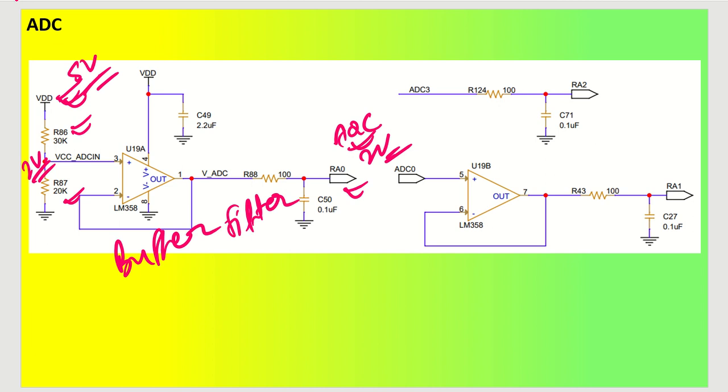Suppose I am reading an ADC value which is coming up as some count, like 300 or 200 or 1000, and corresponding to that my voltage is reaching 1 volt. So what I will decide is, my 1 volt is coming here, it means my input voltage is not correct. Got it? This is how you can check your 5-volt input voltage based on the ADC value that has been read. And this is how you can decide whether to switch off the system itself because the input power supply is not correct. Got it?